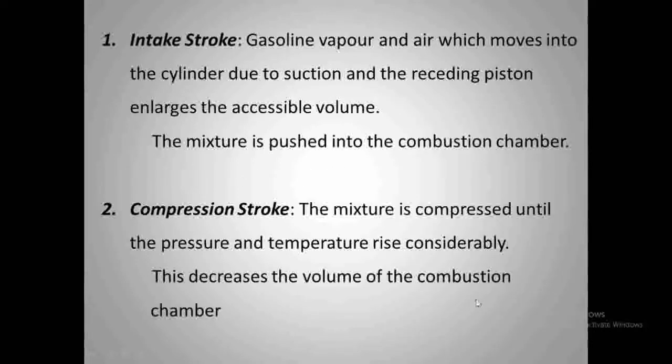So in the second process, the compression stroke, the mixture is compressed until the pressure and temperature rise considerably. If we are compressing the chamber, then the pressure and the temperature of the system will increase until they reach a certain value. The compression decreases the volume of the combustion chamber. So the second one also needs the motion of the piston. The movement of the piston will increase the pressure and temperature of the system and decrease the volume of the chamber.